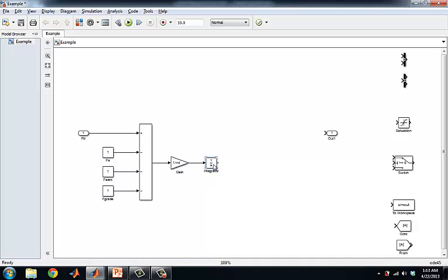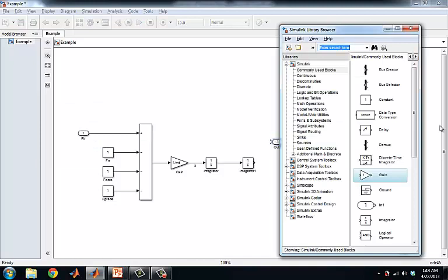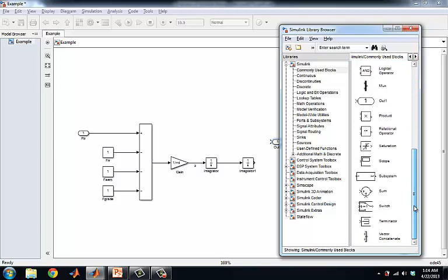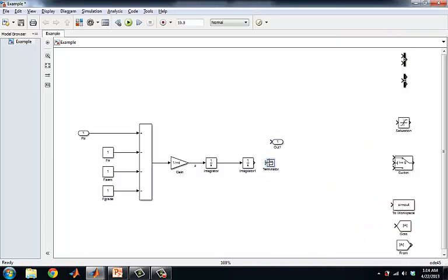This integrator block always defaults to integrating with respect to time. So here we have acceleration, and on the other side of it we have the vehicle velocity, which is what we've been looking for. We can duplicate this integrator block once more, so we can have position. So this signal here is going to be position, and we can just put that to an output. Actually, I'm just going to put the position to a terminator block, since we're not actually going to be using it in this example. And this terminator block just makes this signal go to 0. Okay, so here we have the vehicle velocity V,